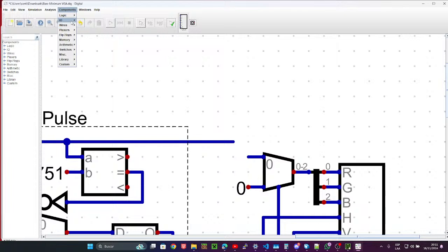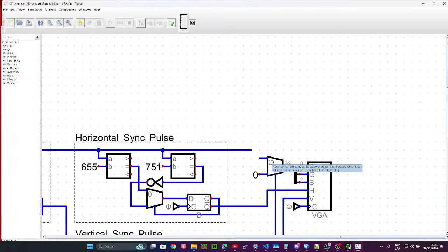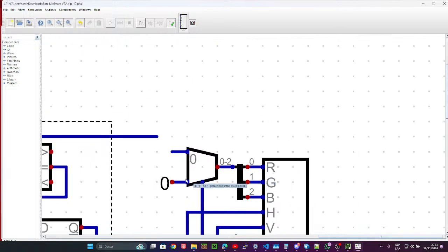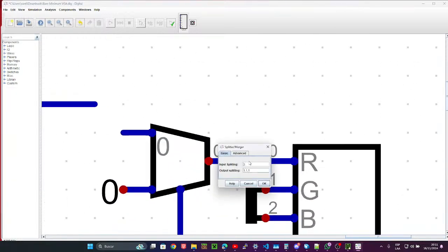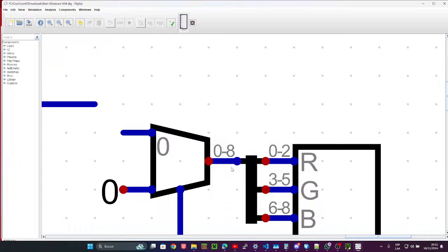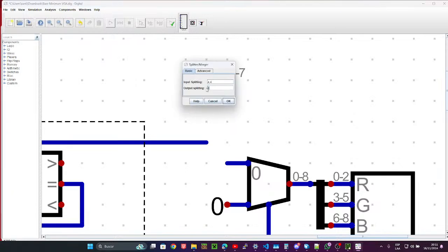10 bits, alright. Here, the multiplexer is just 3 bits. And you do need the multiplexer here because you want the color inputs on the monitor to zero out when you do sync, like when you're not in the visible area anymore. Change this to 3. Change the max to 9 bits. I already changed that. I'm going to give it a constant. Also the constant, I changed it.